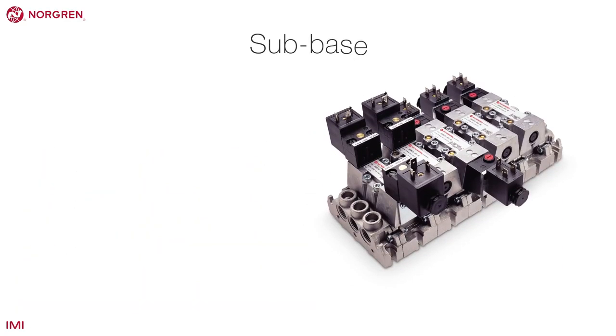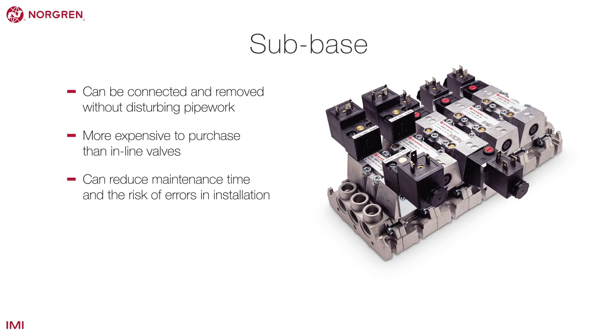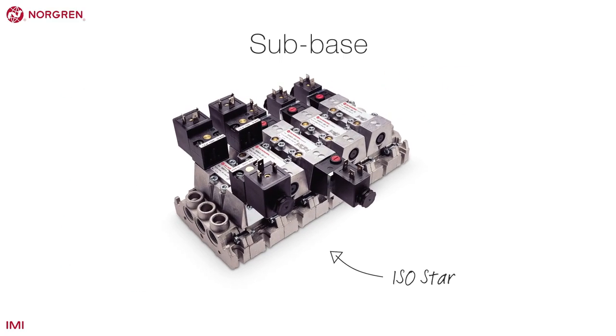A sub-base allows valves to be connected and removed without disturbing pipework. Although more expensive to purchase than inline valves, they can considerably reduce maintenance time and the risk of errors in installation. The valve can simply be unscrewed and removed at the gasket face. Sub-base valves also drastically reduce the number of components required, especially the need for fittings and silencers, as compared to an inline valve. Norgren's IsoStar range is an example of a sub-base valve.